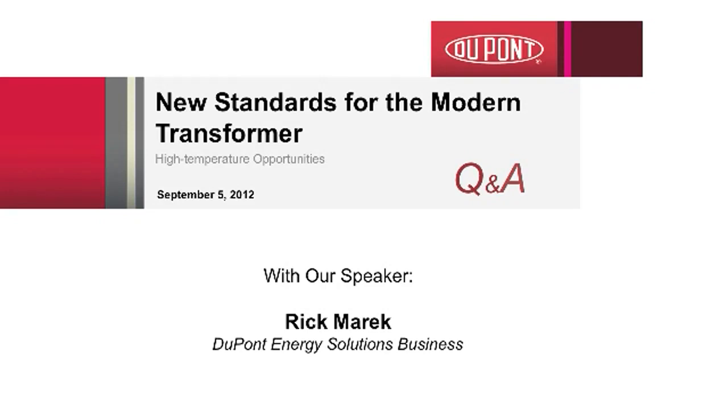All righty, thanks. Here's an interesting question for you. How is the moisture balance between Nomex and insulation oils compared to conventional paper and insulation oils? Actually, they are very similar, and we have recently done some tests to develop the moisture equilibrium curves, and they can be supplied on request.